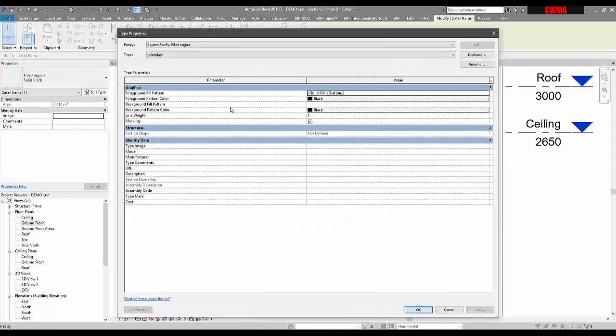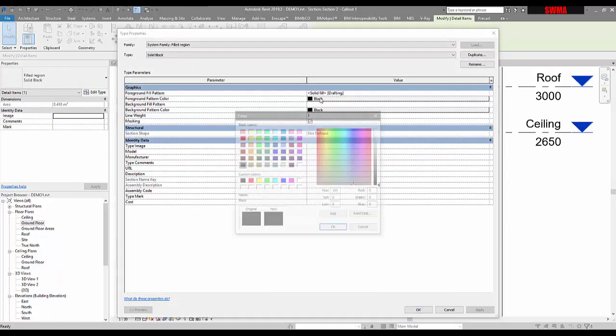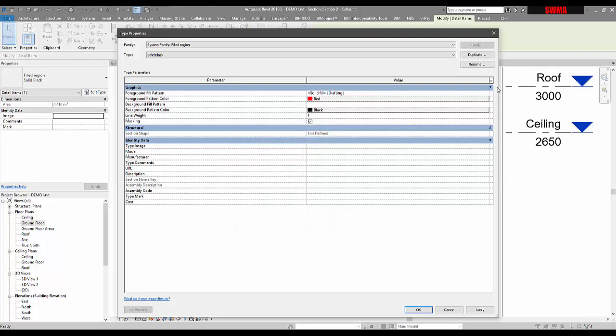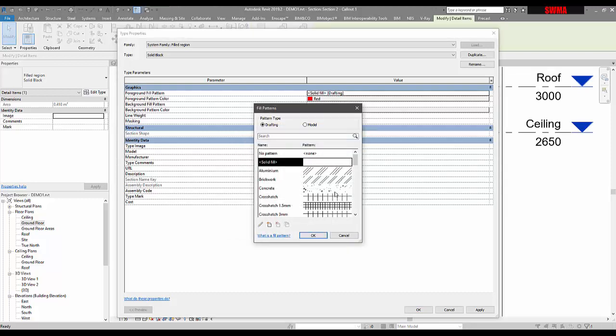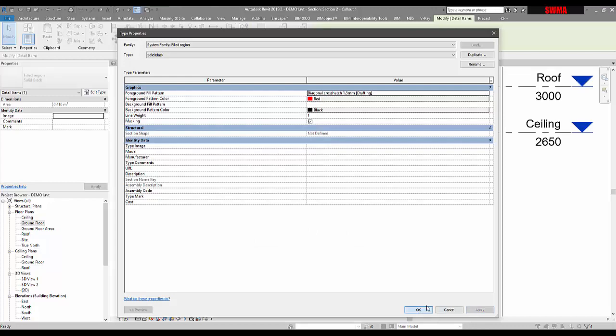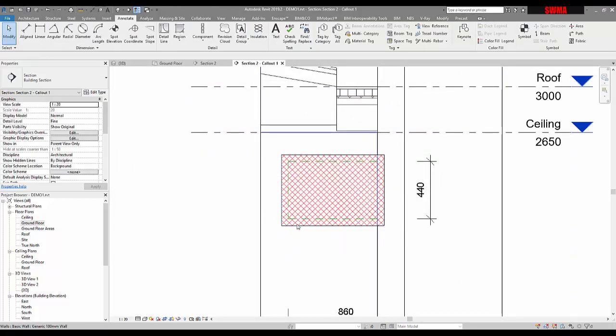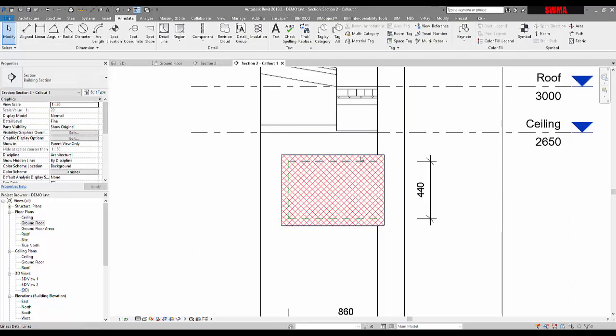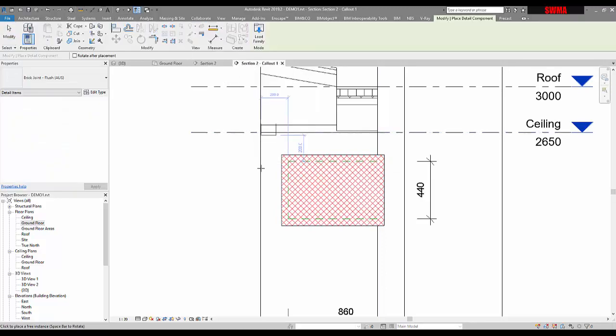And if you need to go and adjust that, at the moment it is filling in as a solid black. I want it to maybe be red, and I want it not to be solid black. I want it to be hatch. So handy little tools like that, to add all that annotation should you not be ready to do everything inside of Revit just yet. Components, so you've got detail components.